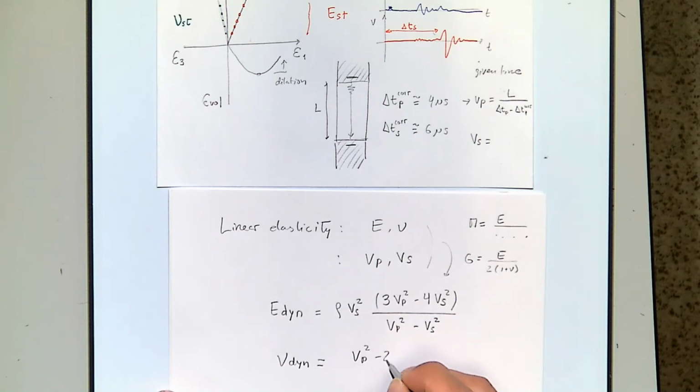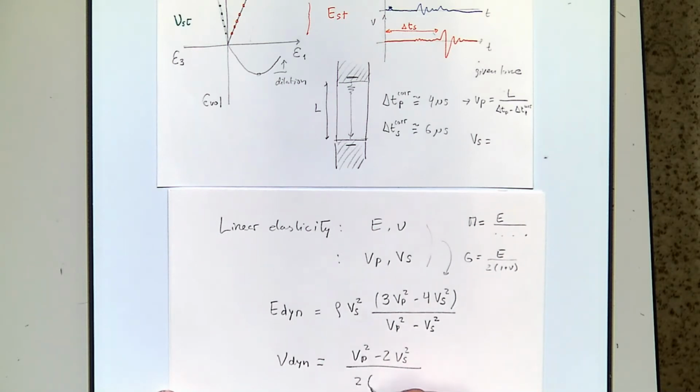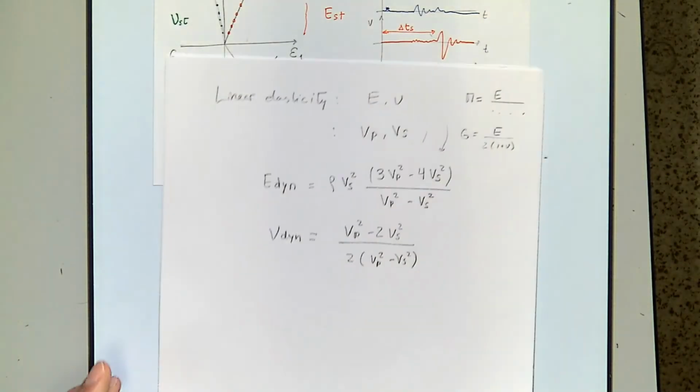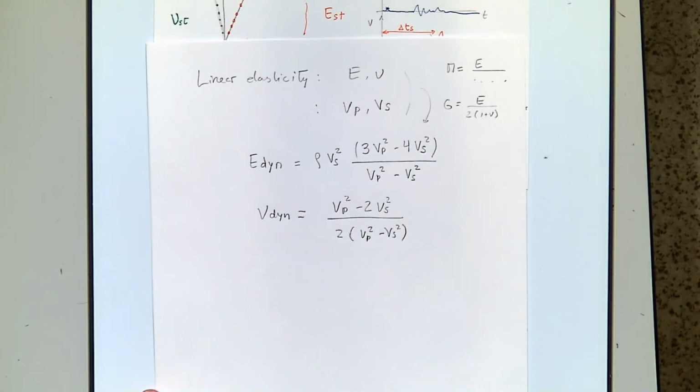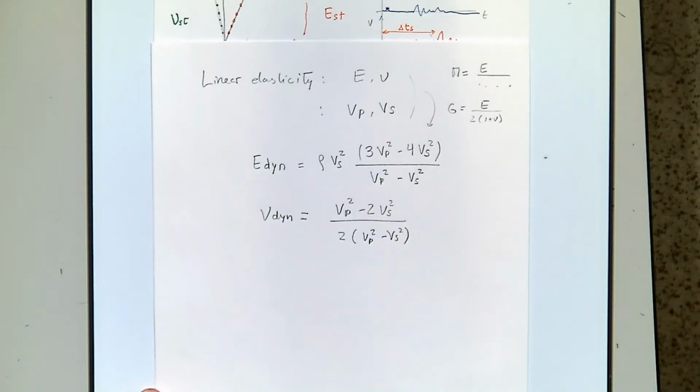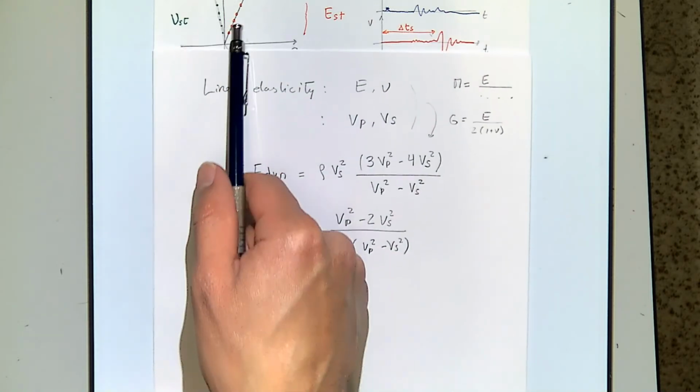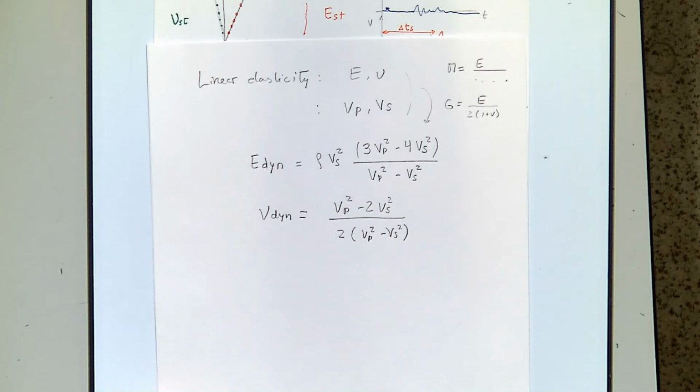And with these equations now you can calculate those two properties, Young modulus and Poisson ratio, from VP and VS, and utilizing the density. And finally, after you do all of this, I'm asking you to do it for just 5 points, okay? I'll give you many more than that, but just do it for 5 points. Select some 5 points over here, do it for 5 points.